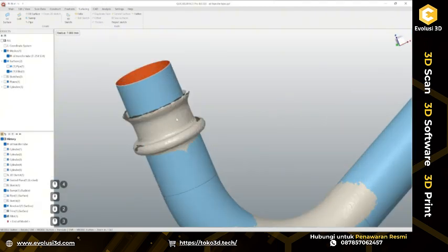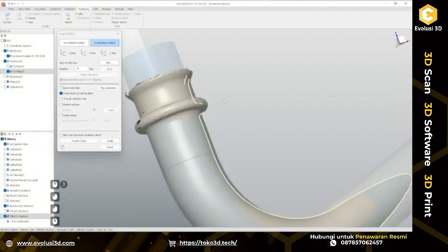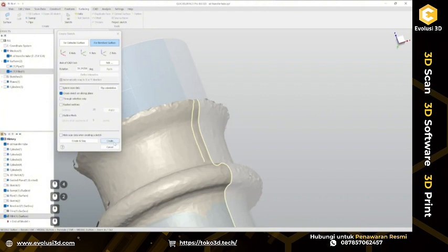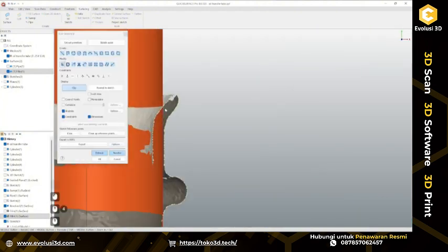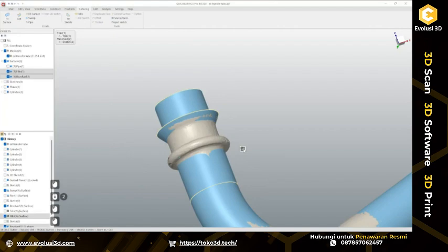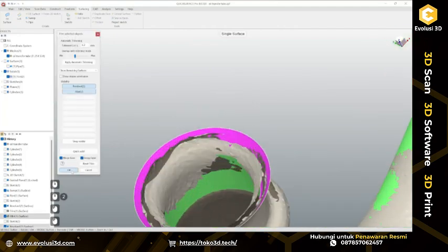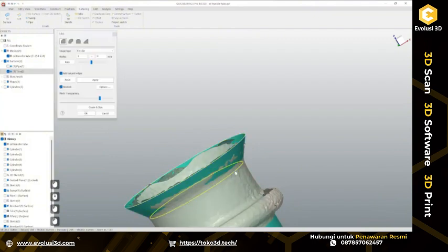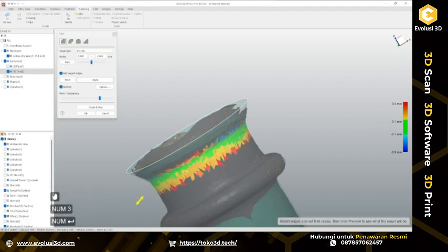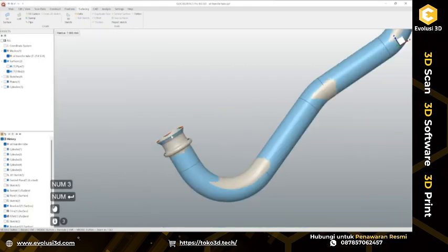Let's go to the other side and create here the same cross-section sketch to define the flare on the opposite side of this pipe. Let's do revolve. Okay, again, trim those two. Add fillet here. So it should be around 3 millimeters, same as the opposite side.